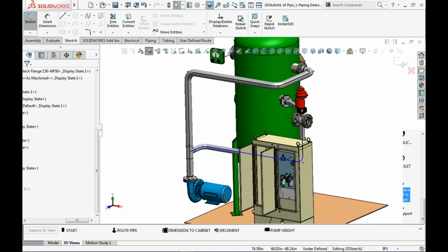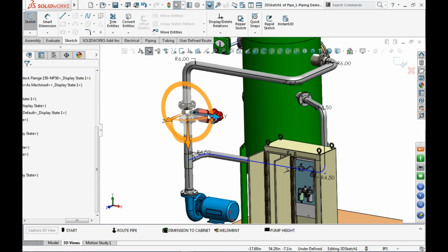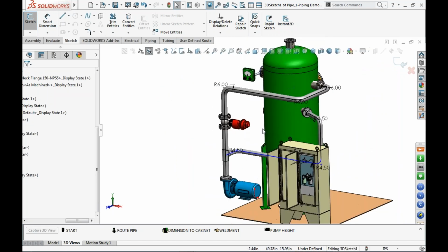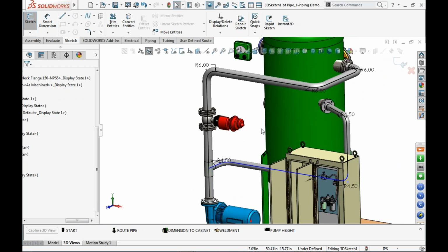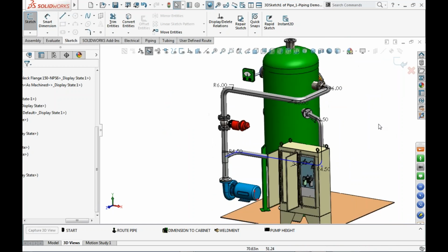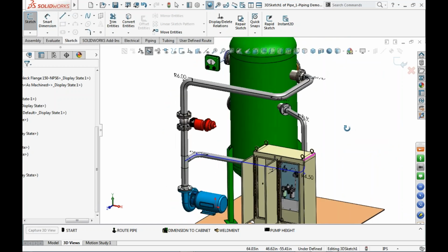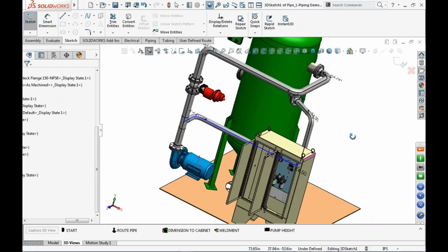And all I'm going to do is drag this, and you can see that it's going to snap to fit on any of my pipe routes. Just fantastic capability. I'm just going to place it over in this area and release. And now SolidWorks is going to allow me to clock this at any angle. This angle is perfect for what I need. And what may not be very obvious at this moment is that SolidWorks has also trimmed back these pipes accordingly. So we've gotten a pretty good pipe run done in seconds. We know that it's visually exactly what we want.